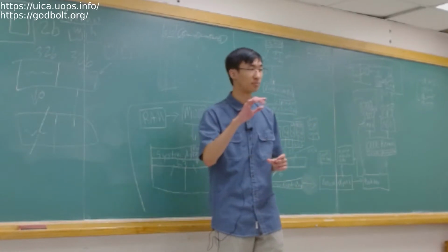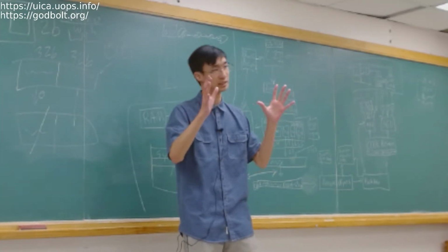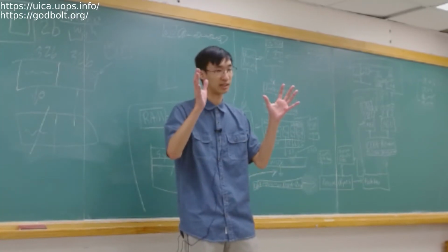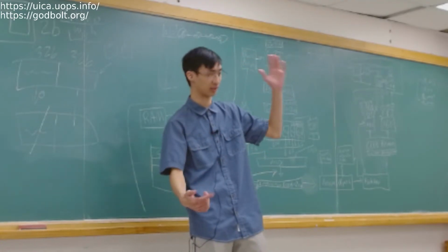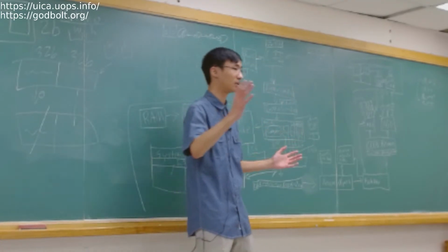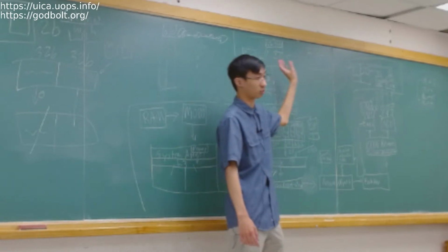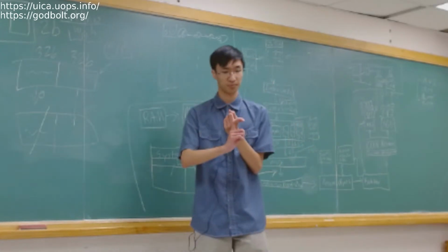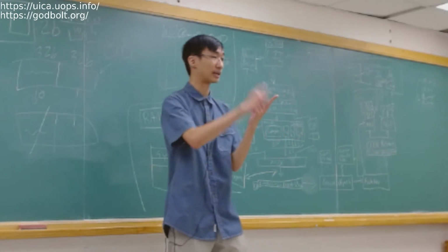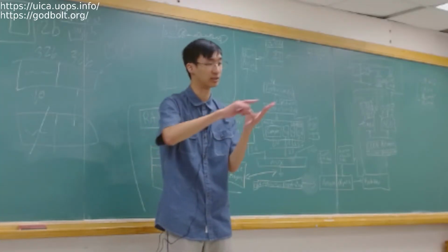Nowadays, we don't really do that because predicting whether or not it's in the cache is really, really hard. You're sitting there like, I don't know if it's in cache, where do I put it, and how do I make it load the next one in the next part of the loop? So what we have are hardware prediction methods, or hardware prefetching methods, that go, okay, if you access a cache line and you access the next cache line, then you probably want to access the next cache line after that.